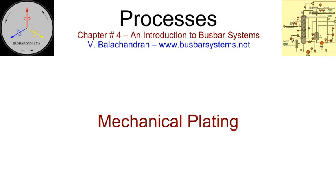It can provide a uniform thin coat of the metal on the substrate even when the component has an intricate profile. Unlike the process of electroplating, which also can provide a thin uniform coat on any profile of the substrate, it precludes hydrogen embrittlement. The component is descaled and cleaned.